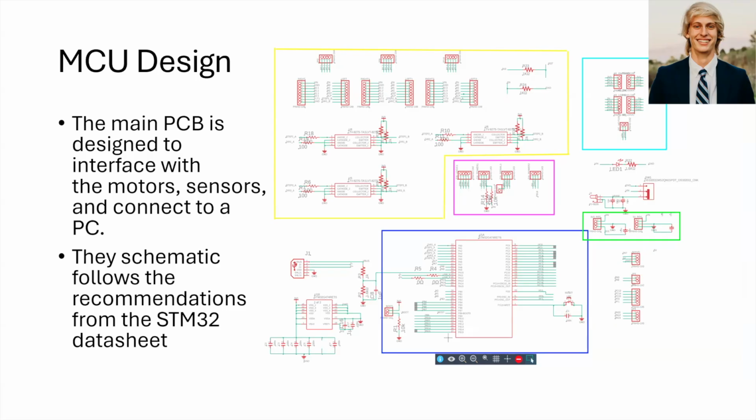The main board, as mentioned before, is centered around the MCU with a lot of motor driver circuitry. And the blue square on the bottom is the basic circuitry for the MCU. And on the top, you see the full stepper layout with optocoupler circuits on the bottom and pin breakouts on the top so that we can easily click the drivers right into the board.